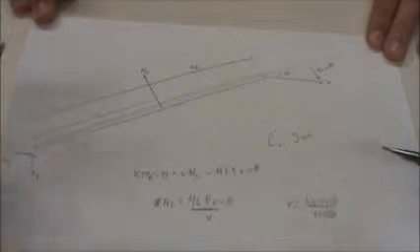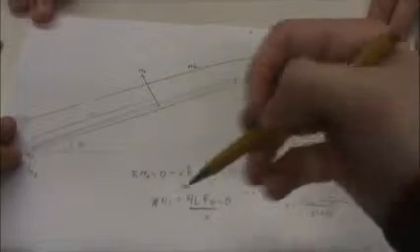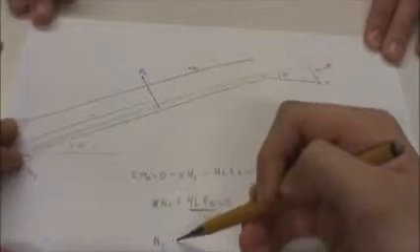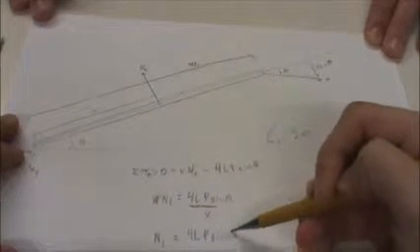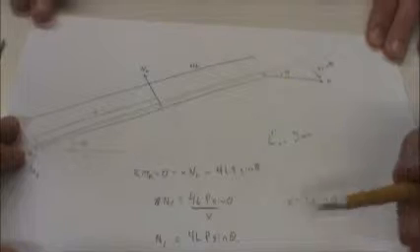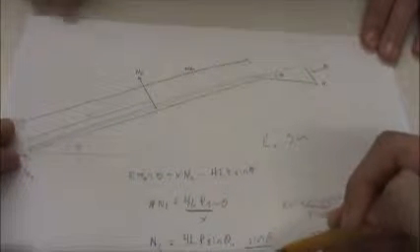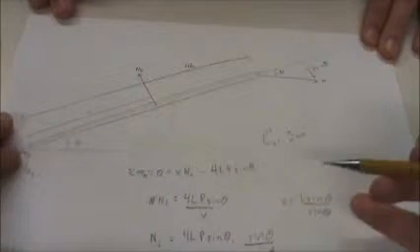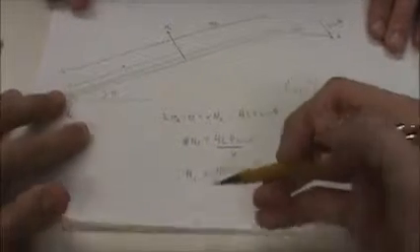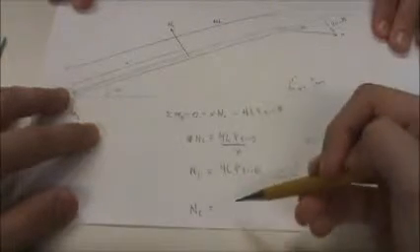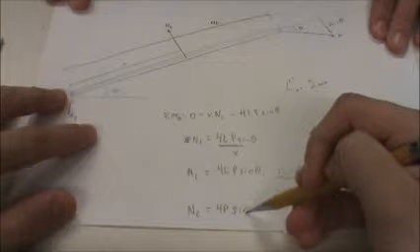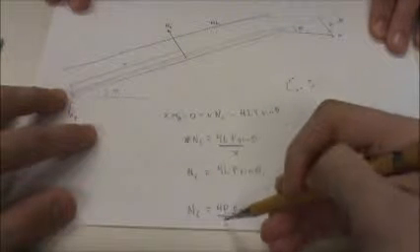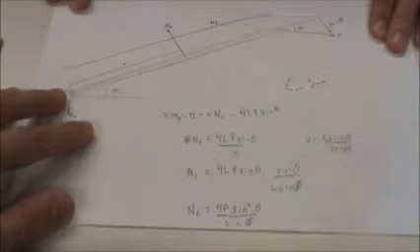We found that just a moment ago. So we substitute that in, and we find that the normal force C equals 4LP sine theta times the inverse of x, which is sine theta over L sine phi. Simplifying this, we get that the normal force equals 4 times P times the sine squared of theta over sine of phi.